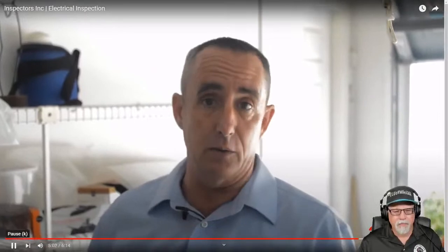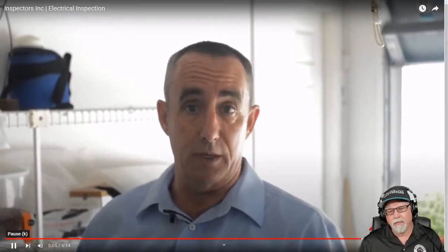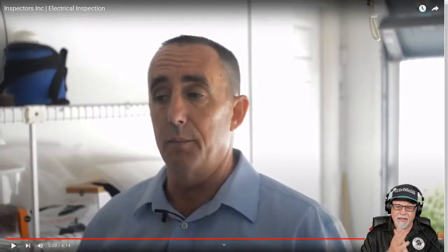Interrupter. Any outlet within 6 feet of water, or exterior outlets, or kitchens or bathrooms, again, within 6 feet of water, should be GFI protected. Okay, let's make this statement here. So I hear this one a lot. The statement is any receptacle within 6 feet of water is required to be GFCI protected.